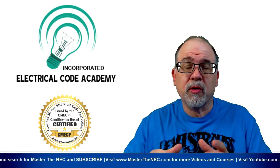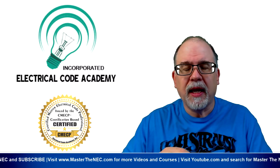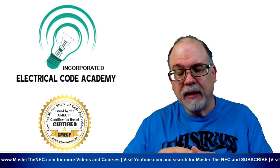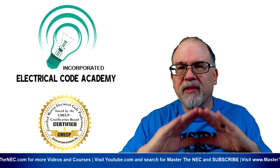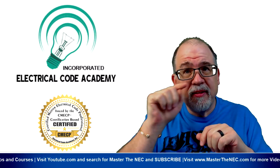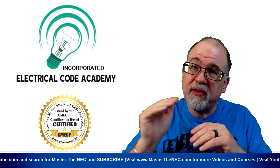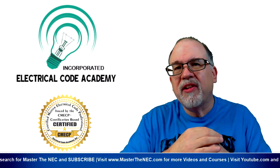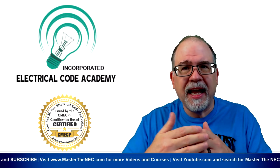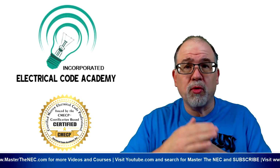Three-phase transformers are delta or Y. Delta is the Greek symbol for triangle, and the Y is also a Greek symbol, and literally the formation of the transformer looks like a Y. Now, what's the difference? Well, the delta transformer looks like a triangle, and you have common connections from A to B, B to C, and A to C. So you have a winding between A and B, a winding between B and C, and a winding between A and C. Typically, when we use a delta and we're trying to derive something like a 120/240 off of a delta layout, we're going to center tap between A and C, and that's what's going to give us our 120 to grounded conductor.